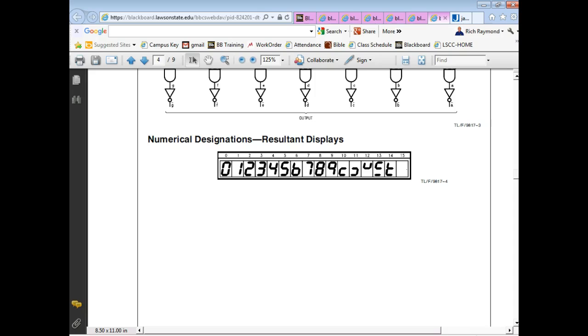What the compatible computers do is that every time it gets a fault, it sends an error code down its bus that you can plug stuff in. We used to have what they call a postcode card that some of your fancier motherboards had built in. I don't know if y'all remember these, but it had two 7-segment displays that, if it failed, would give you a code and you could look it up on a chart. Most of your motherboards didn't have that. So we had a postcode card that we could stick into one of the slots on the motherboard that would capture these error codes for us.